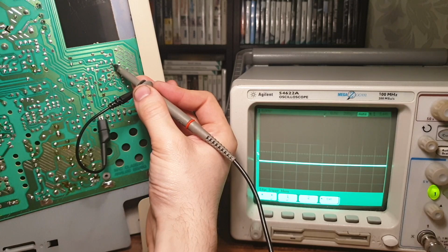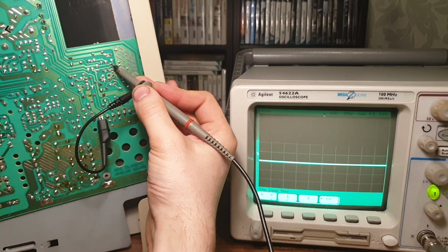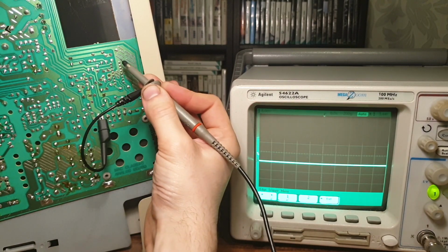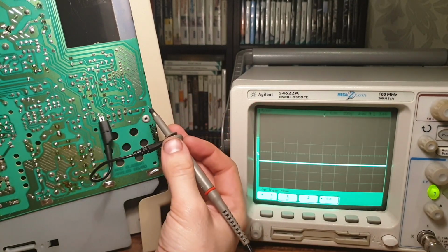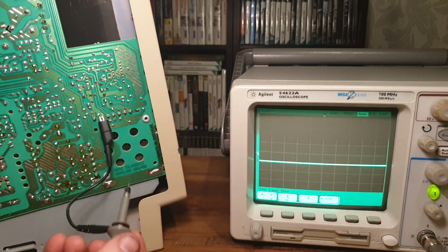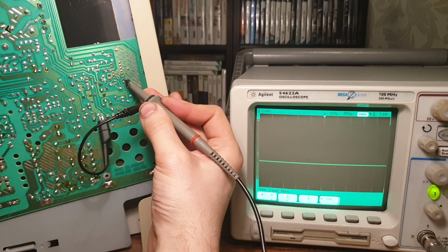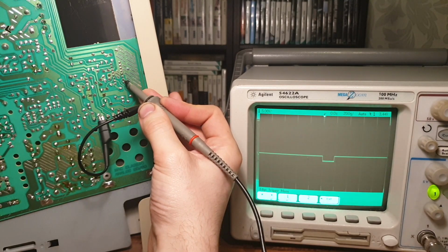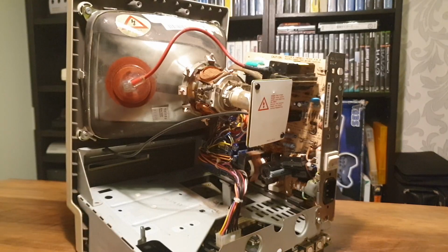Our survey says... Well, there's the problem. We have no output, so of course we're going to have no vertical sweep, because the vertical coil isn't moving the beam at all. And given that we have an input to the chip for the vertical pulse, then it looks like the TEA chip has failed, right? So, let's replace it.